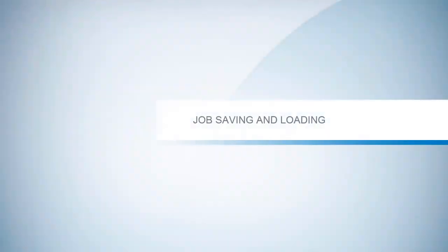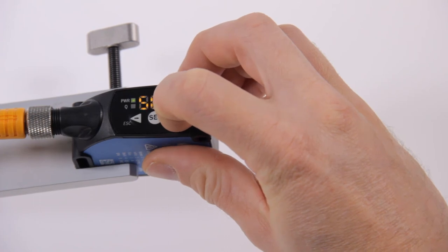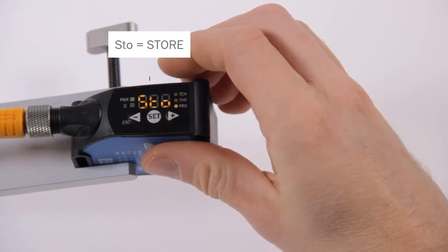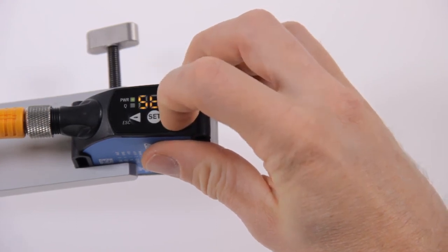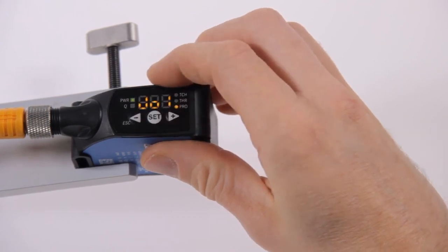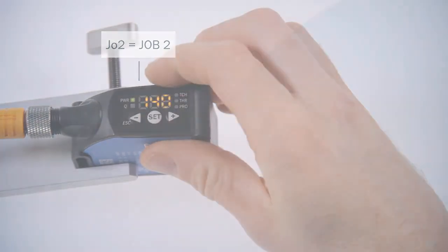Job saving and loading. The sensor allows saving job settings and loading them again. Total number of jobs that can be stored and loaded is 5. Use the plus and minus buttons to navigate to the item Job. Confirm with Set and then select whether a job shall be stored or loaded by selecting STO for store or LOA for load. In this example, a job is stored, so STO is selected and confirmed with Set. Then the job number is selected. In this case, JO2 for job 2 is selected and confirmed with Set.